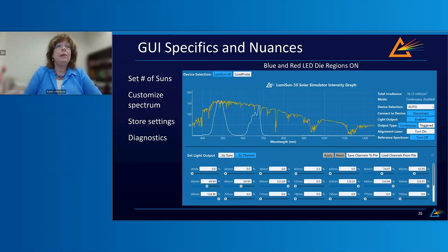With LED solar simulators, it's easy for users to focus on different regions of the spectrum. For example, if you are interested in red and blue spectrum for PV characterization, this is set individually through percent of 1 sun, as shown in the GUI here and on the previous slide. Different wavelengths penetrate to different depths. Blue or UV, shallow absorption near the front surface. Red has deep absorption near the rear regions. So by tuning, you can selectively study which layer of the device is performing poorly.